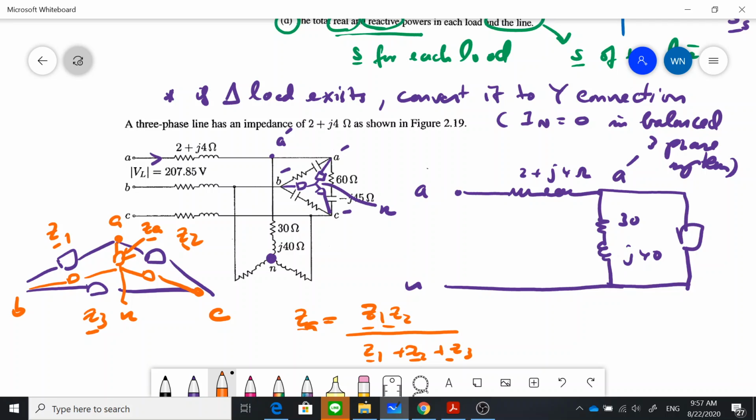So in the transformation, you have to get the product of these two impedances between which the Y impedance is located. Similarly, if you want to find the ZB here, ZB is in between Z1 and Z3, so this is Z1, Z3 divided by the total sum, Z1 plus Z2 plus Z3, right? Similarly you can write the formula for ZC on your own.